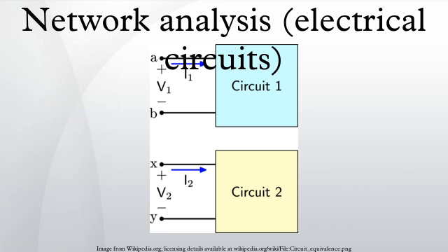It is still possible to use this method if the device being biased has its bias fed through another device which is itself nonlinear, a diode for instance. In this case, however, the plot of the network transfer function onto the device being biased would no longer be a straight line and is consequently more tedious to do.